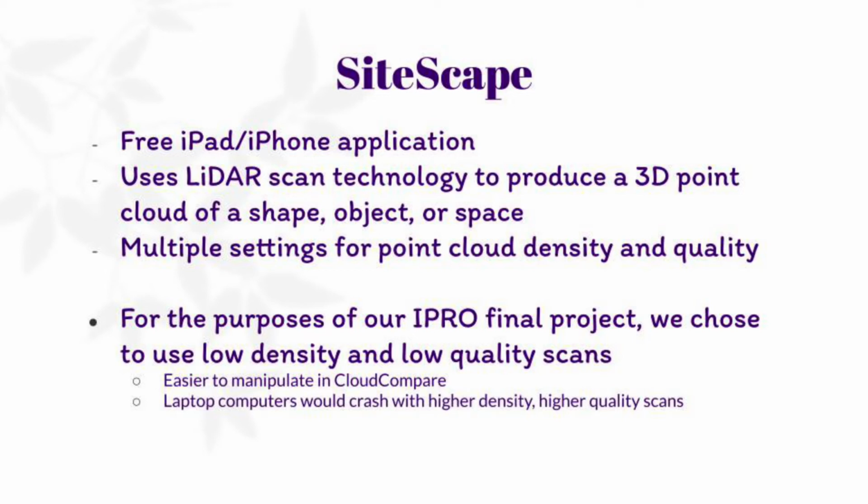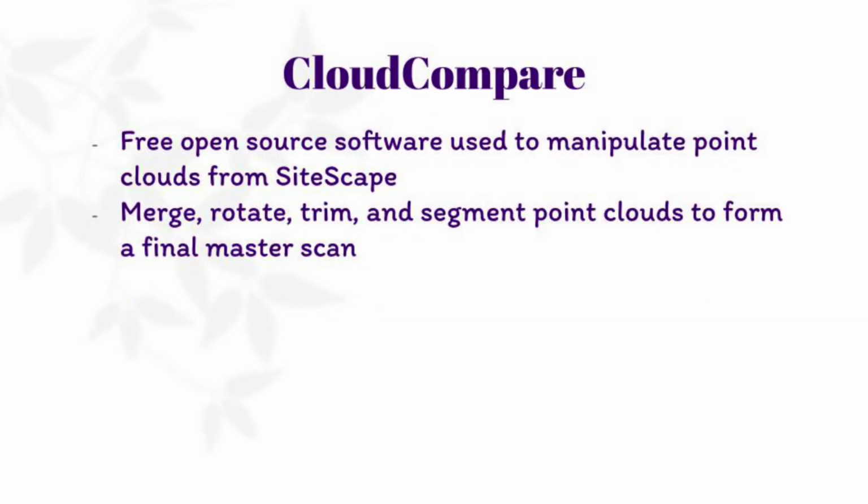our personal laptop computers. In Cloud Compare, I was able to upload multiple point clouds in order to move them around and merge them together to create a room or a set of rooms in a building. Due to the size of the rooms in the 2 buildings we were in charge of scanning, it was almost impossible to get the entire room in one point cloud scan. Therefore, merging was necessary at all stages of the project.